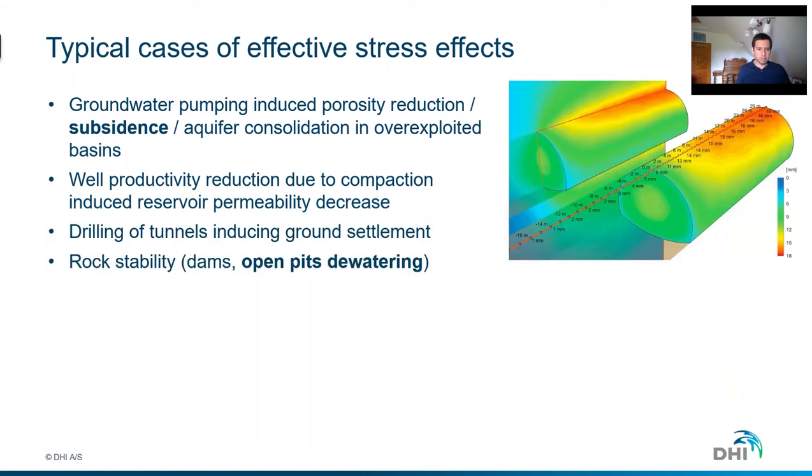well productivity. It's also typical to look at effective stresses and consolidation effects in the case of drilling tunnels. You will typically be interested in analyzing the effect of stresses in the area surrounding the tunnel. There will be a dewatering process associated with the tunnel excavation. There might be a case of infiltration into the tunnel. This will change pore pressure significantly. Therefore, we need to look at effective stresses and consolidation effects associated with this.